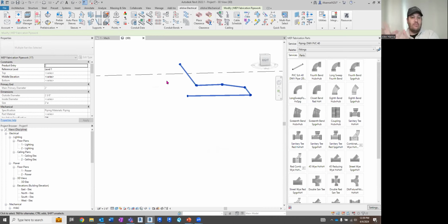When you create your spools, they require you to set up a title block that has your custom templates, the templates that you use every day. So when you spool, those templates are applied to your view. It's very slick and very easy to customize. I was able to customize and set up a couple spools already in about an hour, which is pretty fast setup, especially if you have a lot of those templates and everything ready to go.